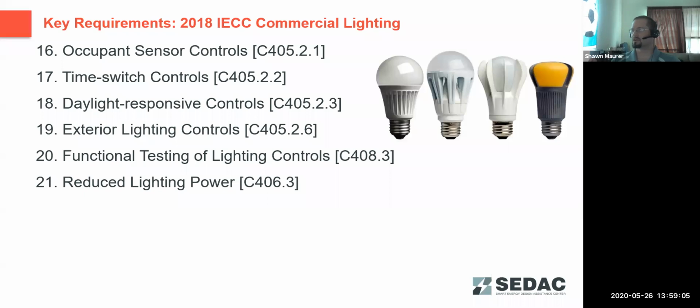to keep your system from being overwhelmed and unable to maintain comfort conditions in the building. Because one of the issues with COVID-19 is if you've got thermal stress in the building, that can increase your susceptibility to the virus. So I don't think they're going to go away. I do think that there are going to be some limited provisions for increasing outside air ventilation on an as-able basis. And similarly, we may see a slight design modification with increased use of purge sections to substantially reduce any risk of carryover from one side to the other.